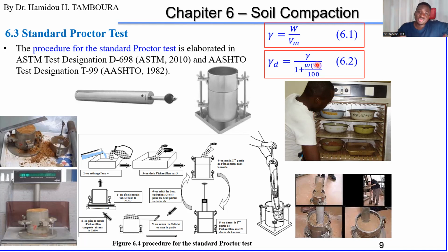So you do this for several tests. As you can see here, the arrow is coming back here. After putting a certain amount of soil in the plate, you put it in this oven. Weigh it first with the soil and the plate, and you can see inside there is a small paper. You write the test number, or on the plate itself, I don't know. That will depend on you.